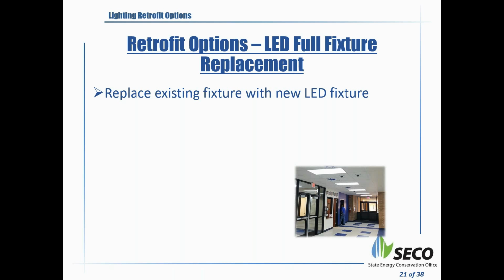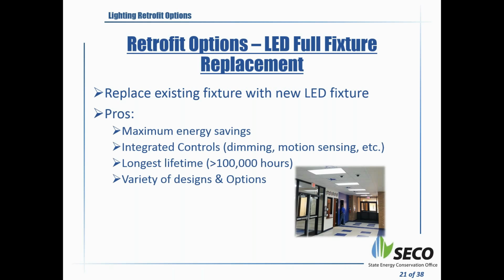So you are looking at replacing the existing fixture with a new LED fixture. You're taking the whole fixture out and putting the new one in, and it is an LED fixture. The advantages or pros of this one is you normally will have more energy savings by doing this retrofit. Integrated controls, so you could have motion sensors and dimming controls as part of these things.